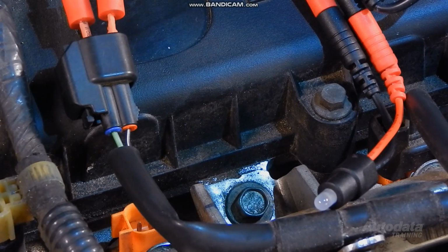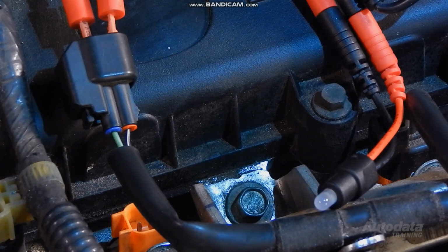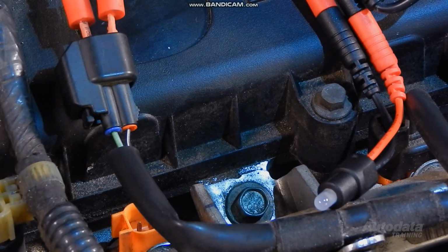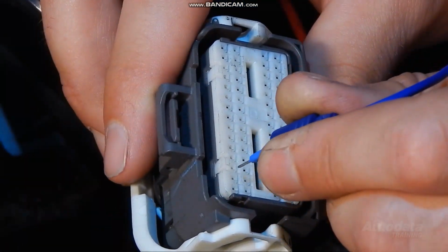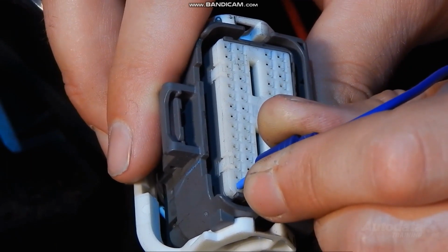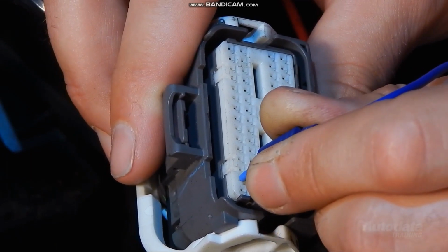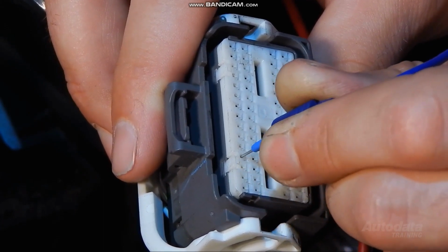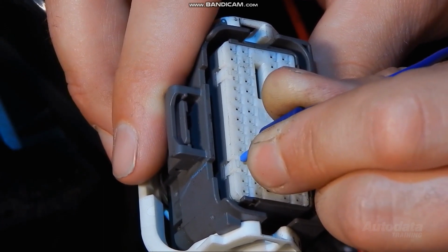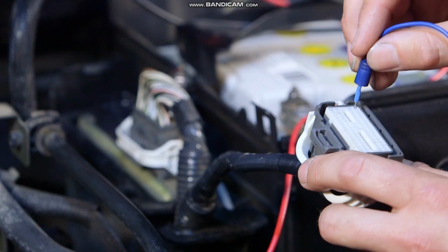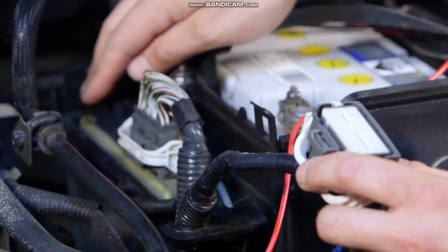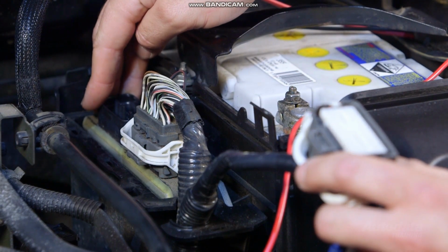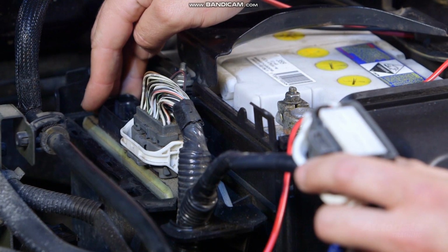No light will indicate a faulty ECM or a short between the control circuit and another ground coming from the ECM. The next test involves checking to see if there's continuity between the injector connector control terminal and any terminal other than the control circuit at the ECM. If no fault is found, then the ECM must have an internal short to ground.